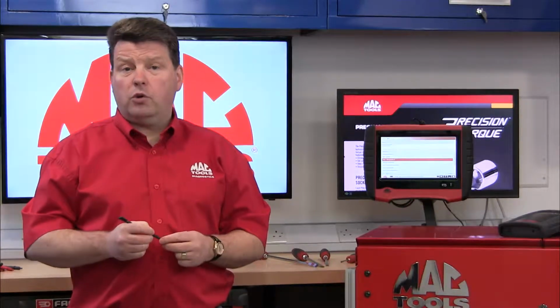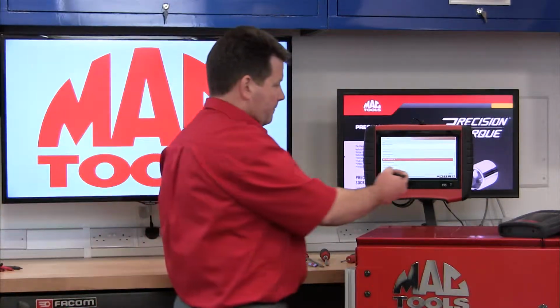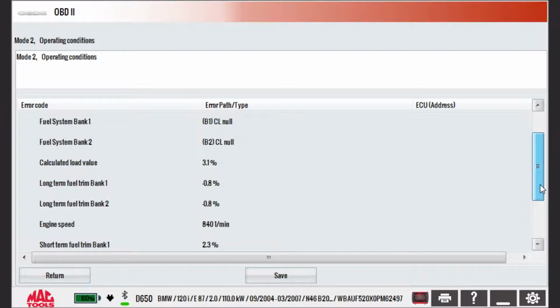Okay, so we have a fault code, but OBD can also give additional information that may help, especially if the fault is intermittent. This is where mode 2 is used. Selecting mode 2 takes you to operating conditions. We're given the code in question, which is P0013, and useful values that were recorded at the moment the error was stored.